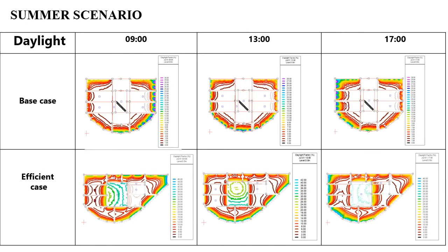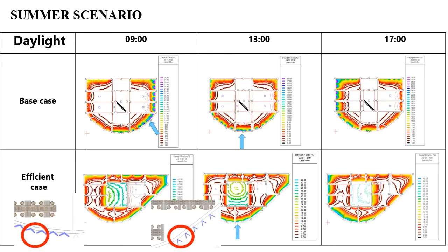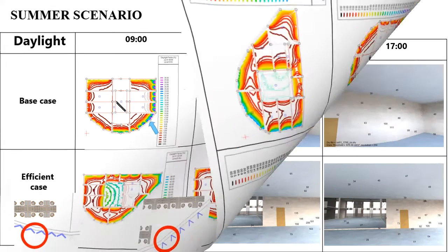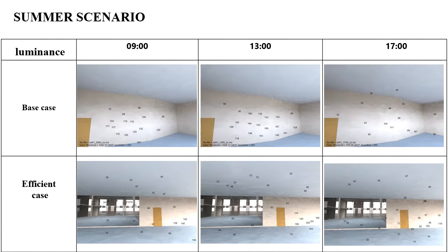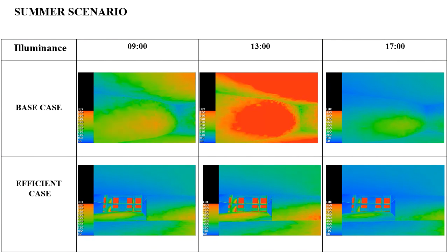The summer simulation results show the efficiency of kinetic facade shading in controlling solar radiations penetrating the building indoor spaces. Moreover, the percentage of shading plays a significant role to achieve the visual and thermal comfort. The results show here that increasing the shading percentage helps to achieve indoor comfort by decreasing solar radiations entering the building. The illuminance ratio was decreased significantly in the summer scenario by using kinetic facade shading.